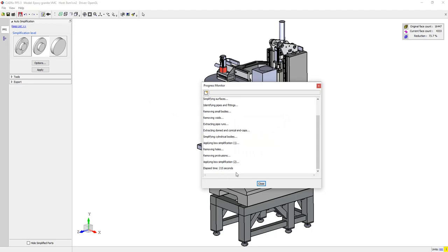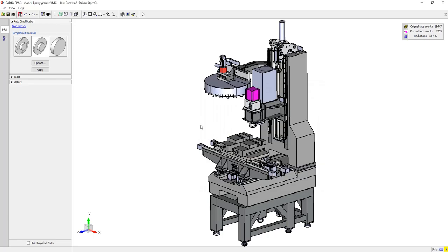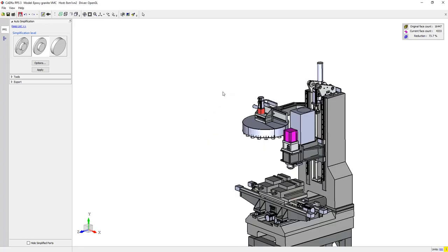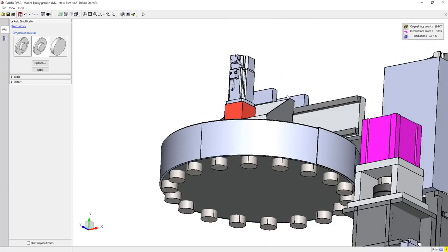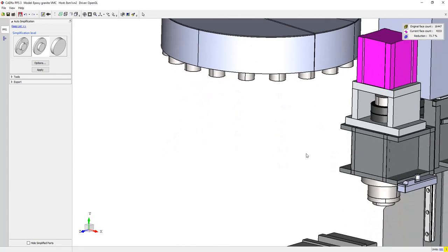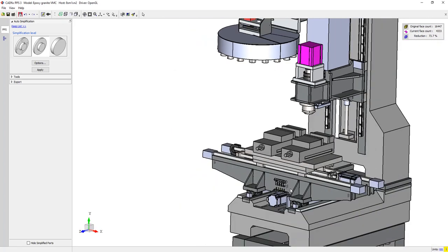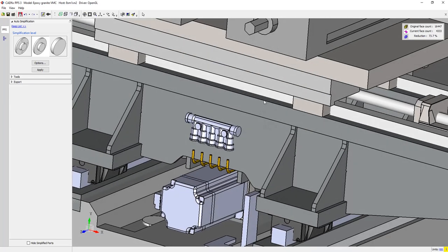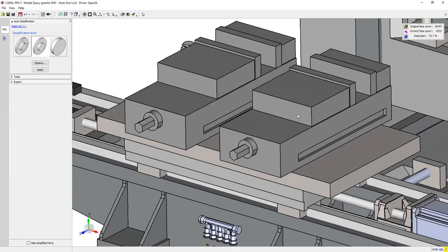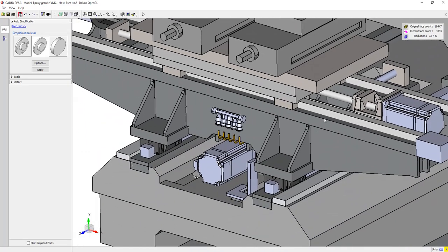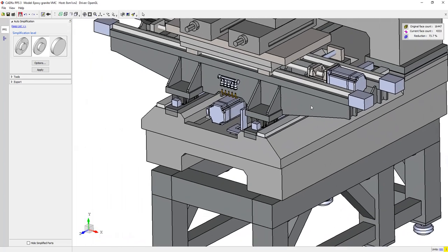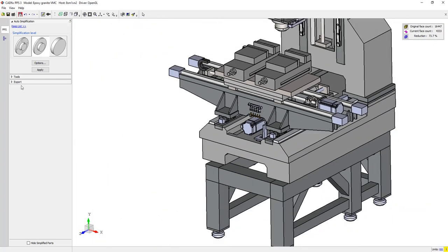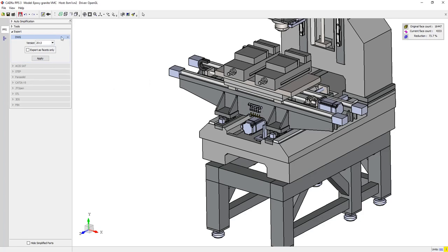And in the top right, we can see we've removed 74% of the faces in the model. So 3.5 minutes and around a high 70, 80% reduction in data probably. And looking at the result, we can see how the box and cylinder simplification has intelligently determined appropriate candidates for simplification. The model has retained this outer envelope. It's obviously visually recognizable as the model which we read in, but with a significant reduction in the total data.